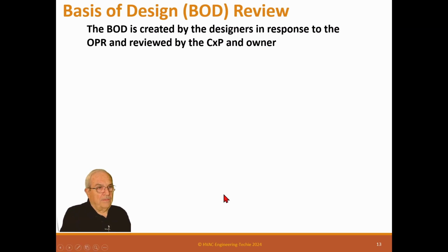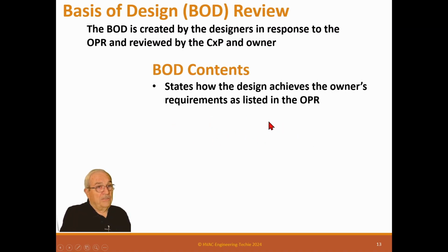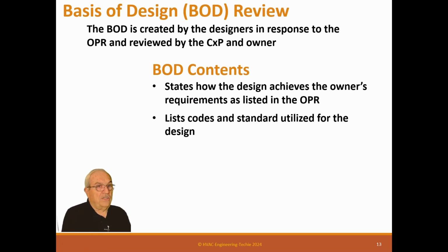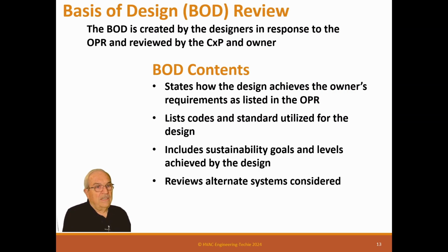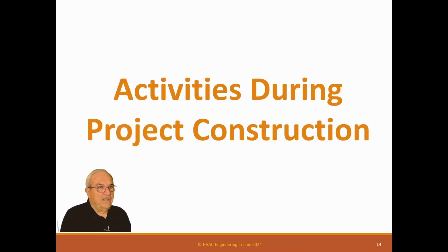I've had many jobs where the owner asks me to do the BOD, and that's not my scope. I didn't do the design. I can't actually do the BOD, and you'll see why. The BOD contents states how the design achieves the owner's requirements as listed in the OPR, lists the codes and standards utilized for the design, includes sustainability goals and levels achieved by the design, reviews alternate systems considered, and I wouldn't know any of that, so they have to do that.